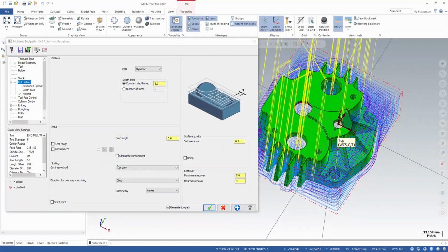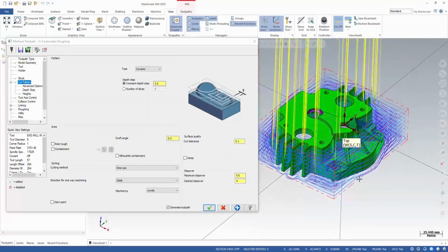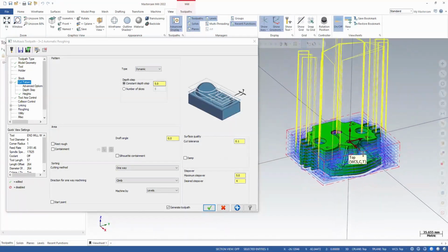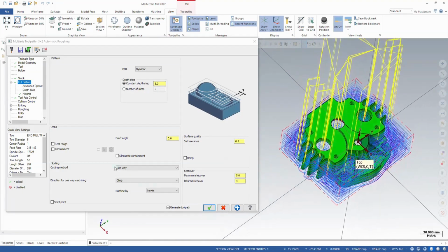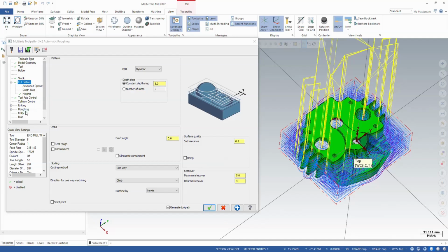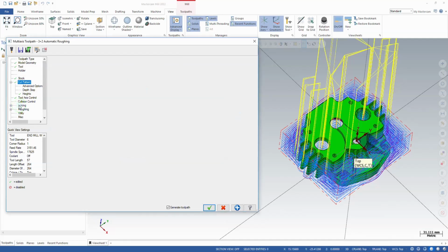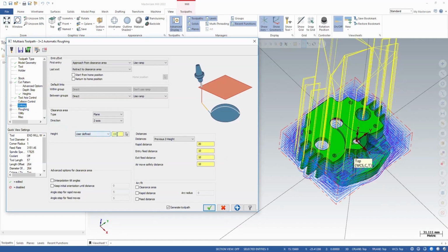So I didn't finish that here yet, because for example I can see straight away that the retractions are too high for my machine if I use the long tools. So let's go back to, let's say, linking, and we can change that.